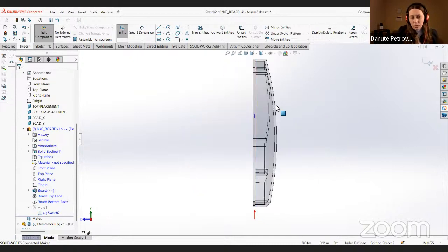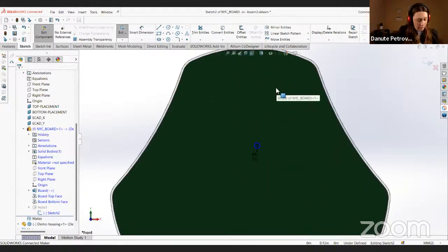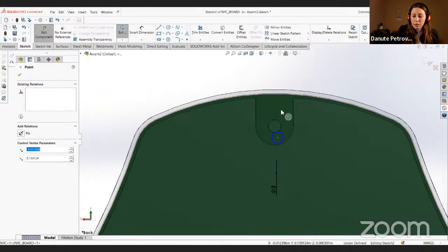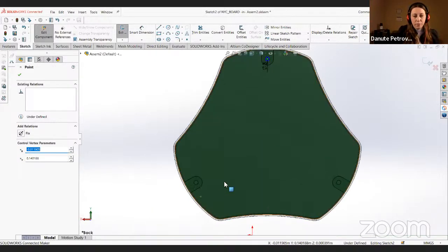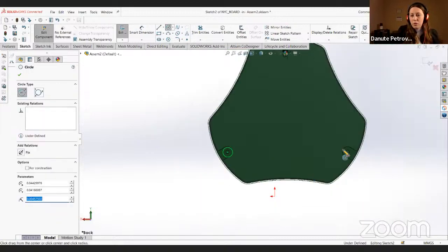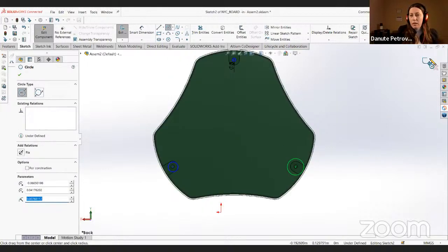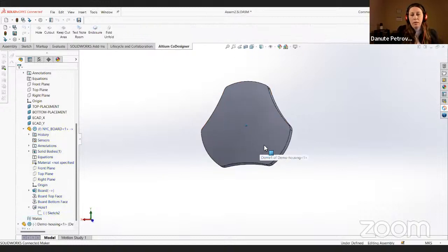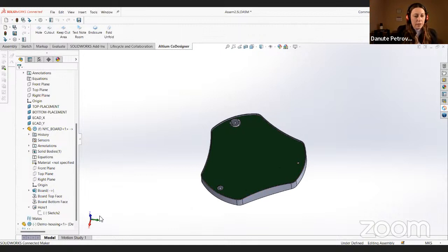Yeah, this is also something which I don't use often, and that's the reason I'm not too used to it. So you have to go into the sketch and then position everything. Otherwise, it's showing the Altium features, which are just the size of the hole. But once you're in the sketch, you can place different holes in different places and finish the operation. And of course, later you can also adjust the position more precisely, or the size.